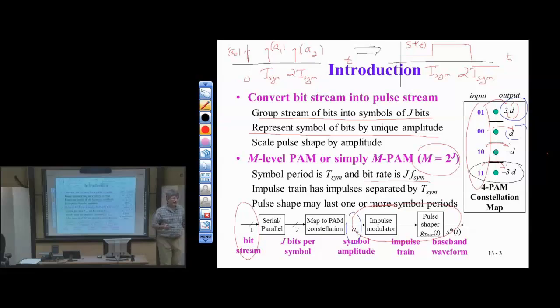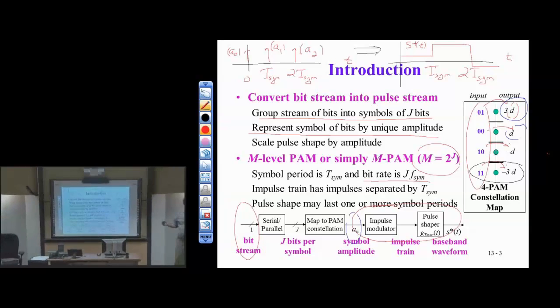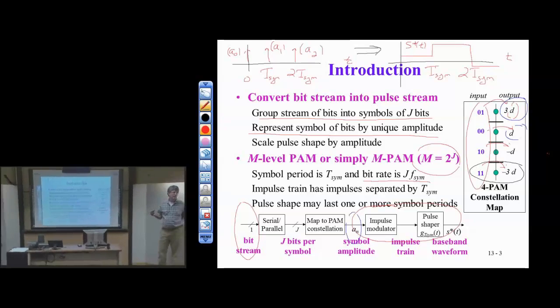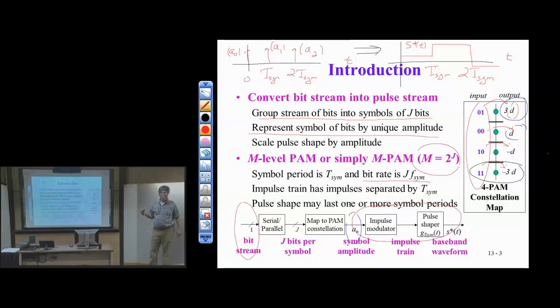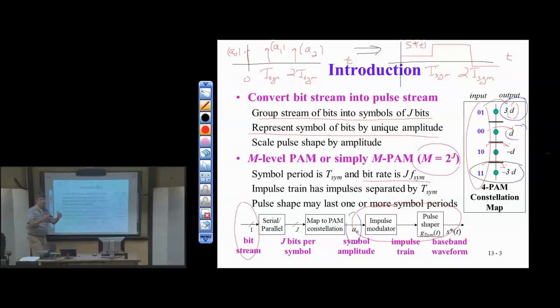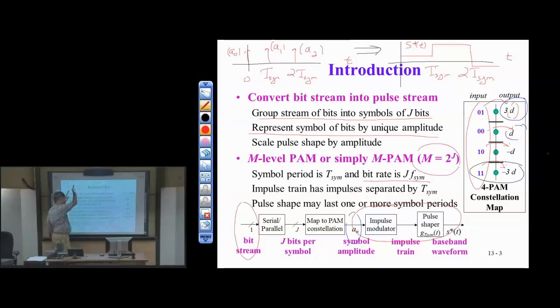So you're saying the symbol amplitude is multiplied by that impulse train, and then the pulse shaping block is tapping into the pulse that you want? Yes. Do you remember, when you convolve with the Dirac delta, all you do is shift the signal you're convolving with and scale it by the area? So this Dirac delta mathematically is A1 delta of t minus capital T sim.